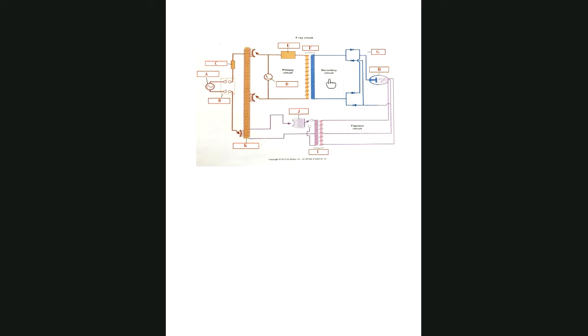That's important to recognize, because step-up transformers increase voltage. If voltage goes up, current has to go down, because they work in tandem. So if a second part of that question asks about the current, you would know it was going to be decreased because the voltage was increased.